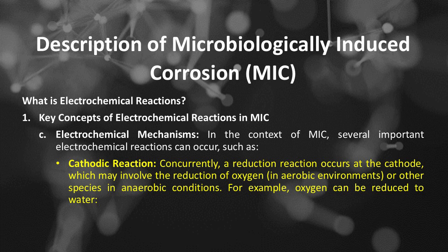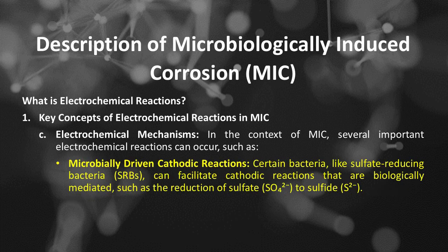Concurrently, a reduction reaction occurs at the cathode, which may involve the reduction of oxygen, in aerobic environments, or other species in anaerobic conditions. For example, oxygen can be reduced to water: O2 + 4e- + 2H2O → 4OH-. Microbially driven cathodic reactions. Certain bacteria, like sulfate-reducing bacteria, SRBs, can facilitate cathodic reactions that are biologically mediated, such as the reduction of sulfate, SO4 2-, to sulfide, S 2-.